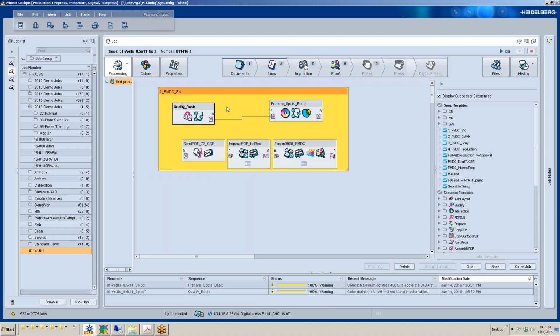Pre-flighting includes user-specific pre-flighting checkpoints. You user define these, basically. Decide whether you want to turn them on or off. There's about 100 different checkpoints. You can have warnings or errors, so levels of severity of what we're pre-flighting.